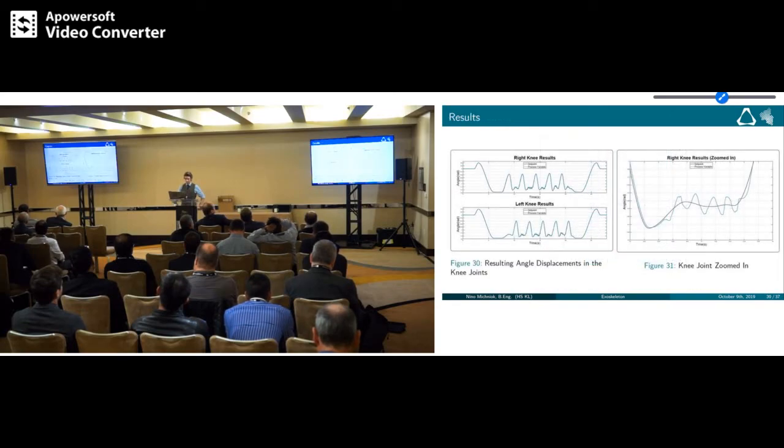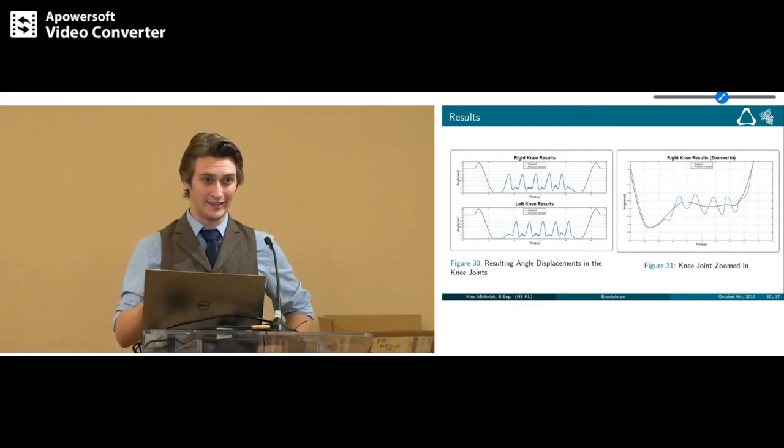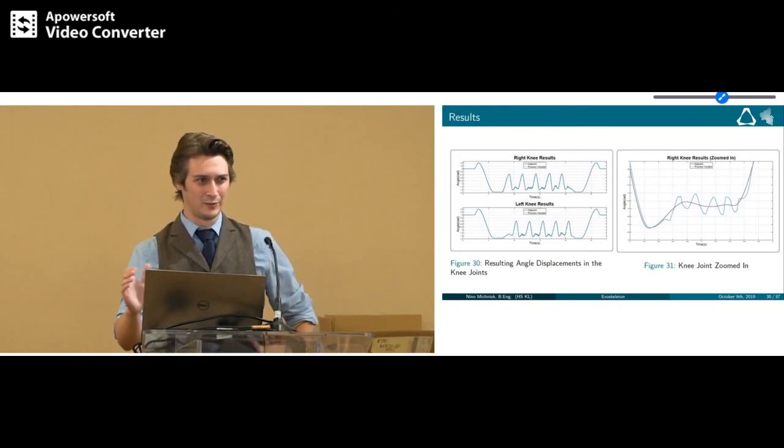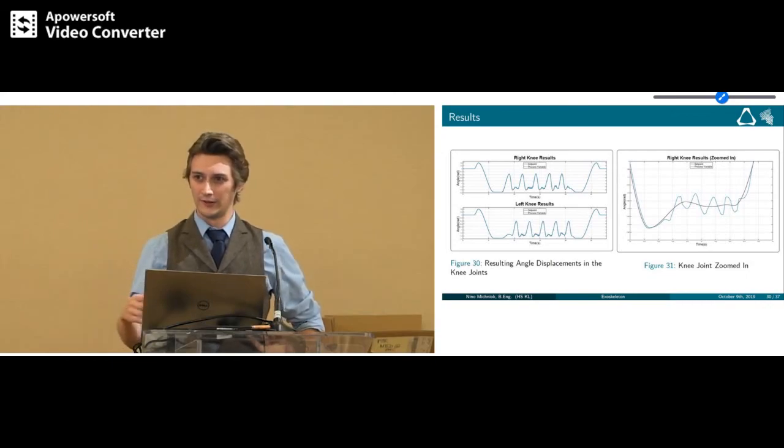The results, I've already mentioned that. Unfortunately, the position control tends to oscillate during the single leg contact. This is the result of the right knee. I've zoomed it in at the right to make it more obvious. This is probably because I used the derivative gains in the PID controllers. I didn't know that at that time to avoid these, but this would be a great entry if any student of our university should continue this work, to avoid these derivative gains.